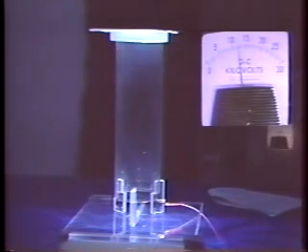What we see at relatively large particle densities is particle motions that are complicated by the motion of the air itself, induced by both the ions and the particles. This is typical of practical precipitators, which are used for air pollution control purposes.